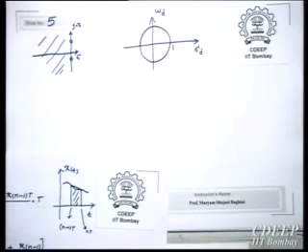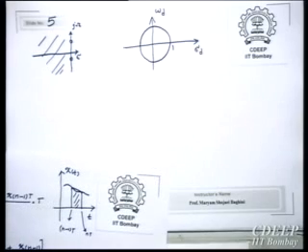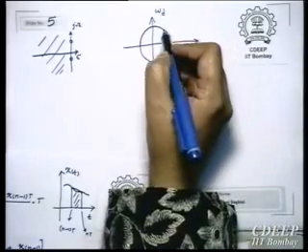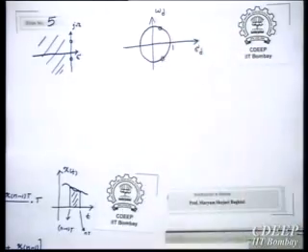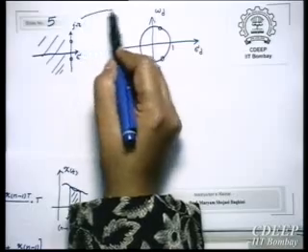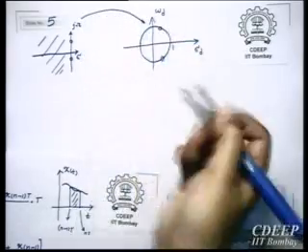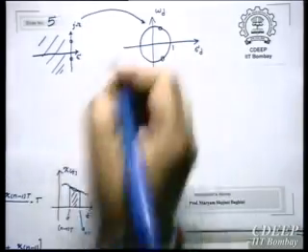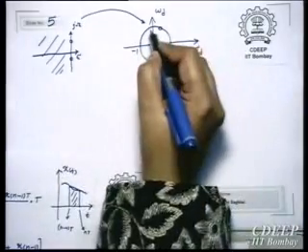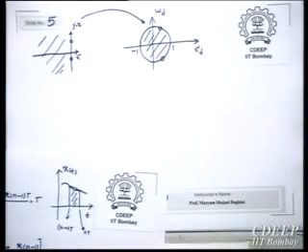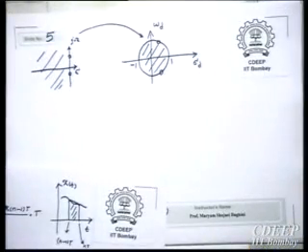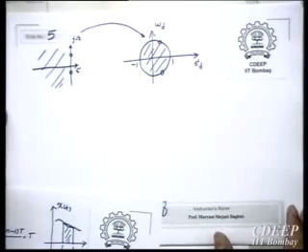So that is interesting, because then we don't lose anything, right? If we have loss, we will still get loss at those frequencies, which was not already available for us. So this will come here. Therefore, j omega will be mapped onto the periphery of the unit circle, and the left side of j omega, of course, will be mapped into the inside area. Okay, so this is for the bilinear transformation.